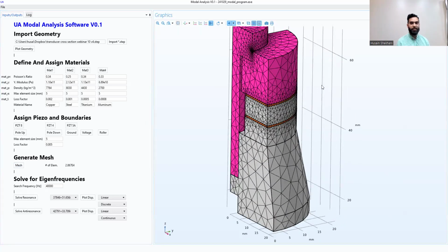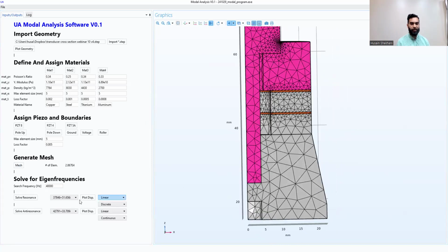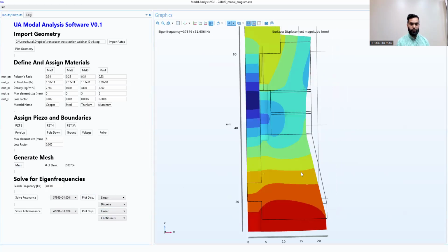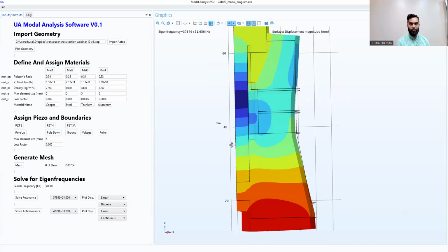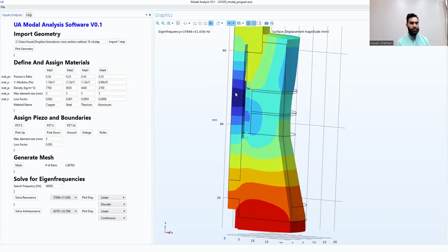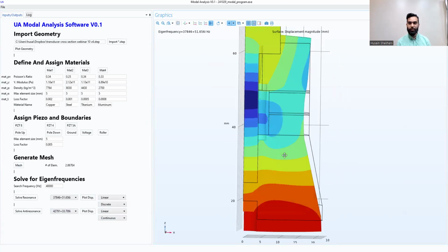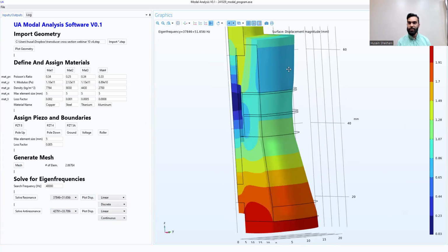I want to machine something in there and I don't know where to hold it. So what do we do here? So using this banded thing, we see that there's zero displacement in the bolt. Well, that's not really a good place to hold it, but if we can put the color bar up here, the lighter blue, it seems like there's the least displacement on this top face.